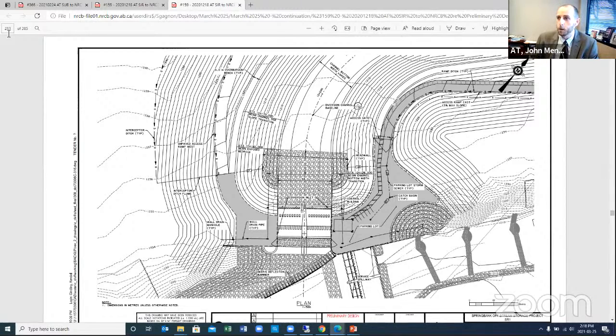I know I'm throwing a lot of numbers here, but that's 6.5 meters above the service spillway, and above what our design operating levels are. So if water continues to get higher than we intend to operate the structure, it would flow over the auxiliary spillway to provide a secondary flow path for water within the river, and to keep the water surface elevations upstream controlled.